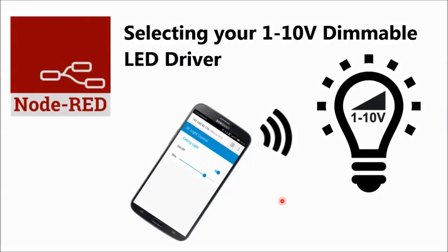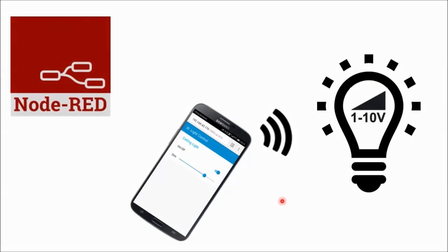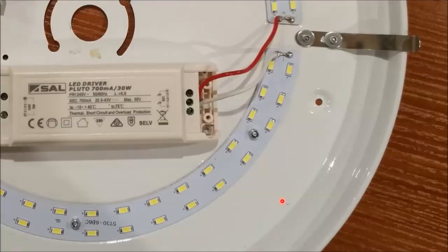In this section I will provide some information about LED driver selection. If you want to replace the existing fixed output LED driver in your light fixture with a dimmable 0 to 10 volt driver, you will need to know the LED voltage and current. To check this, you will need to open up the fixture and check it. You will find something like this. This is the LED driver.